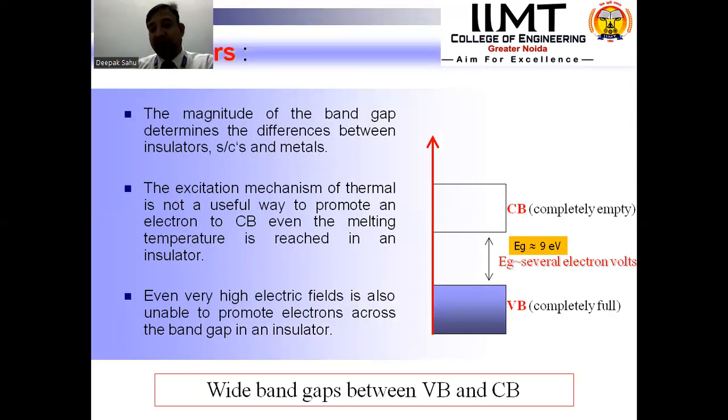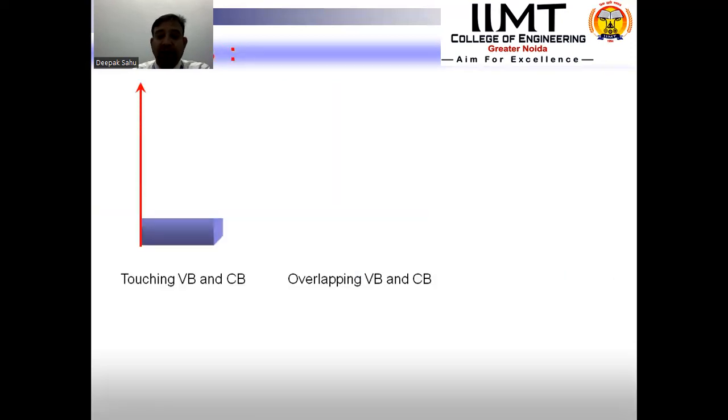Now, insulators, as we can clearly show in the diagram, never have any free electrons available in the conduction band, since the energy required to make an electron jump from the valence band to the conduction band is very, very high. In providing this energy, the electron may jump, but the basic crystalline structure of the system will melt down due to the high energy levels.